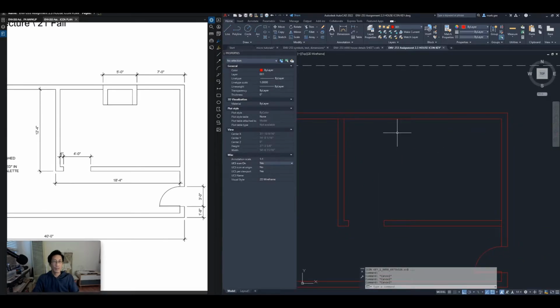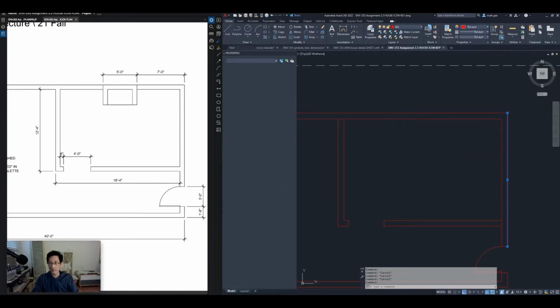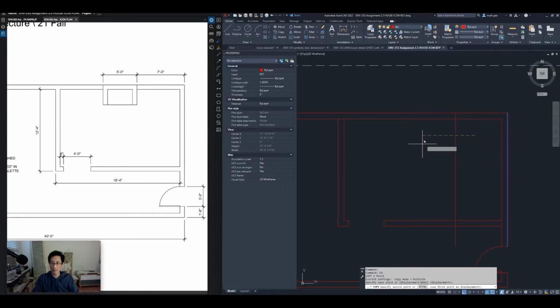Okay. 7 feet over from the exterior corner, 5 feet wide, and I didn't put a dimension in the other direction, but I think it was 36. So we'll put that in. So copy, now do another copy of a line here, 84 inches, which is 7 feet.